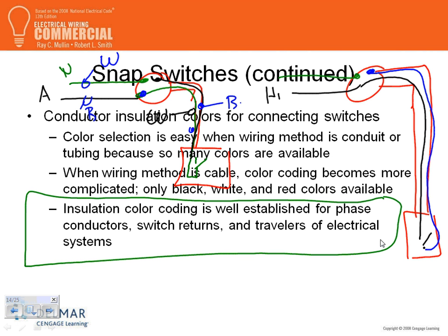Mr. Bew? As far as code goes, all boxes, unless there's a raceway, have to have a neutral wire in them, switch boxes for lighting. Thank you. Right? So if you use MC, you technically couldn't do that. MC, thank you. That's 2011.